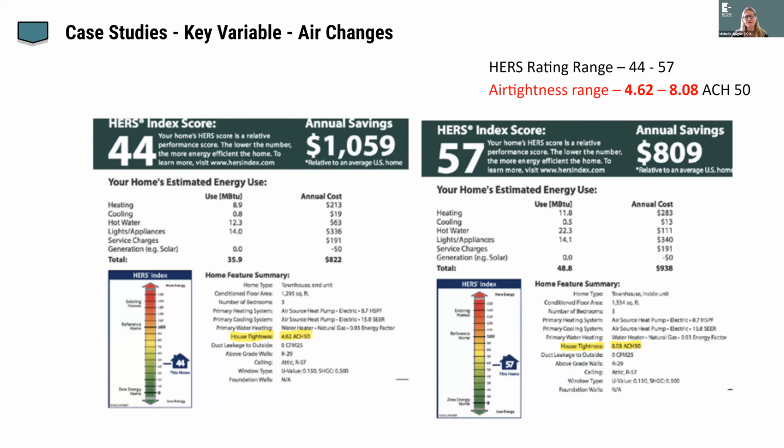In this case, our issue, and New Ecology was actually on this project, was less about the air barrier to the exterior, which was pretty continuous and not such a huge issue. The bigger issue was compartmentalization to the interior, which is also important, especially in multifamily, where you've got demising walls and units next to units and above units. And you want to make sure not only that there's good acoustic separation, but that no one's smelling what you're cooking next door.